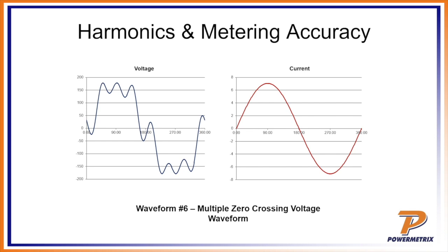But anyway, the point being that the reality of this waveform, this was based on a cheap AC inverter. If you go down to the hardware store, buy an AC converter that you can plug into your cigarette lighter adapter, if you looked at that voltage output with an oscilloscope, that's what you're going to see. You're going to see a square wave. Once again, a lot of harmonic content, given that's a square wave. Really bad for your equipment.